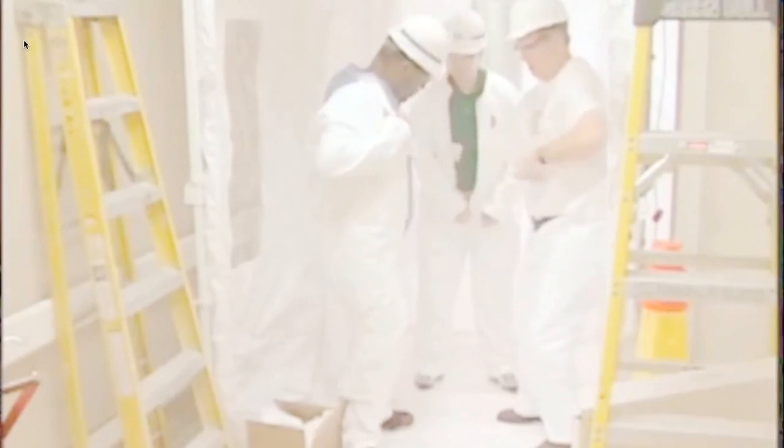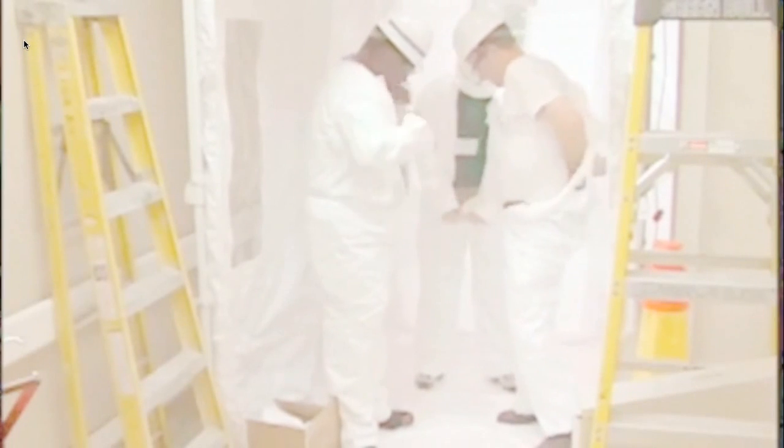During typical Class 3 or 4 projects, workers will either need to put on disposable cloth or paper coveralls or use a HEPA vacuum on clothing before entering a clean zone. The use of an adhesive walk-off mat is one method of controlling dust at the entrance and exit of work areas. One or more mats should be used to capture debris from the workers' feet or from a full revolution of debris container wheels. These mats should be changed daily or more often based on the use and amount of dirt. Or assign a worker to damp mop the exit and traffic pathways as required to control dust and dirt.